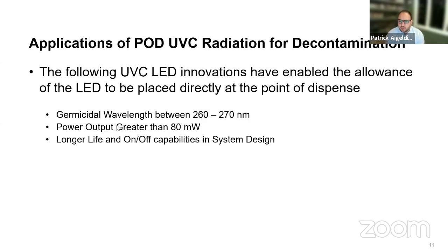So the industry as a whole, growing better substrates, investing in LED technology has allowed the industry to grow from a nascent 10 milliwatt output to 100 milliwatts plus. For many of these single LED, long life, point of dispense applications, there's a threshold of 50, 60, 80 milliwatts that can be used for system design to allow a single LED to provide disinfection performance.